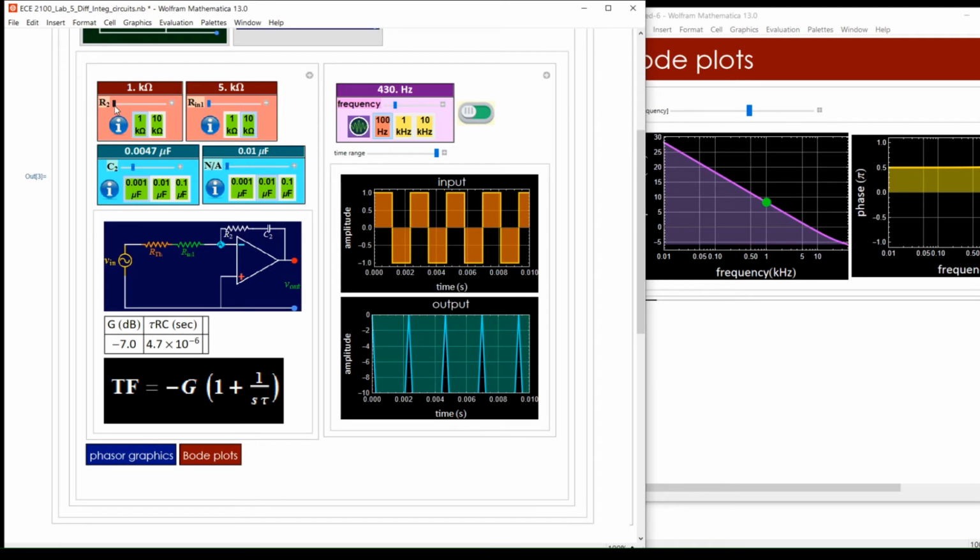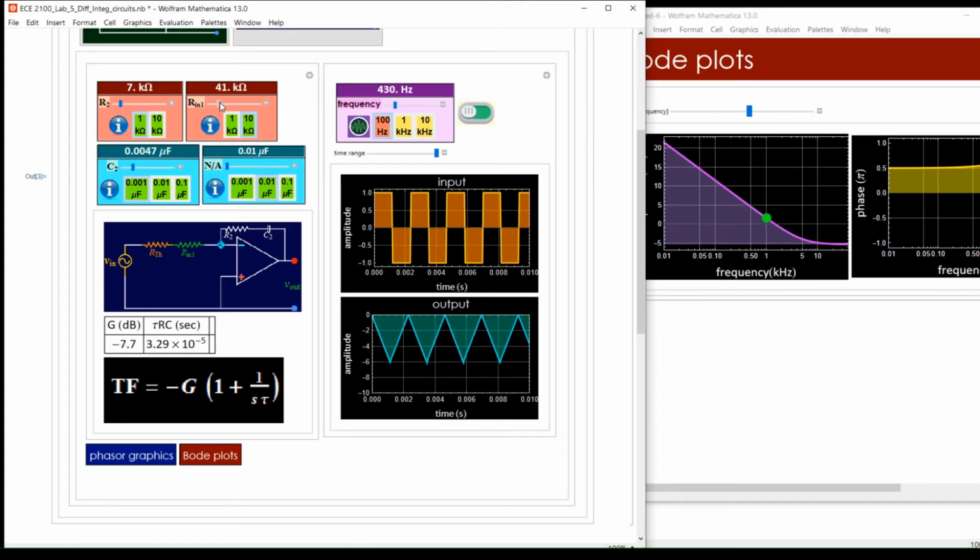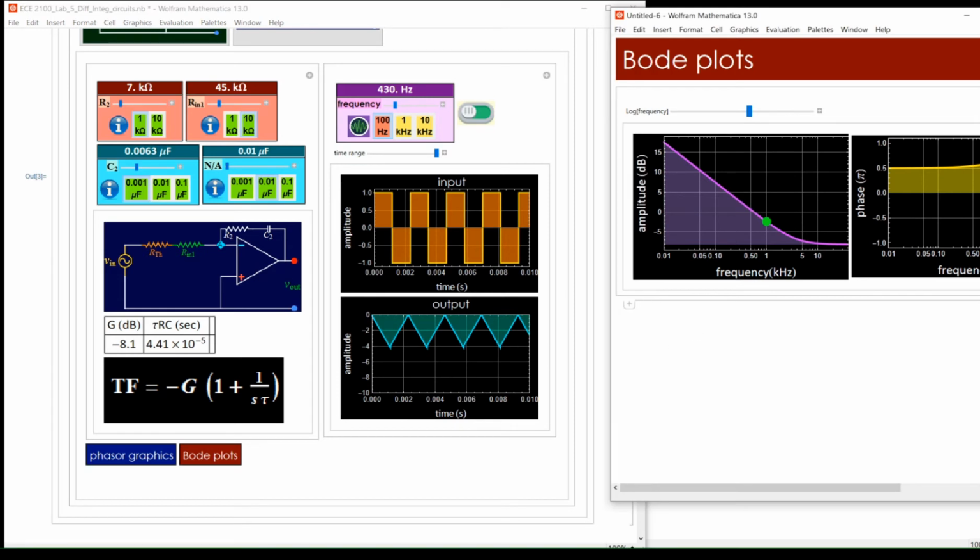The idea is that while there is a bit of latitude in choosing the components, for the sake of uniformity in the class work, choose components such that the Bode plot does not deviate too much from the default. The point is to demonstrate the low-pass behavior, that is, signal decreasing from a few hundred Hz to several kilohertz while still within a measurable range for the oscilloscope, that is a few volts to at least over 10 mV.